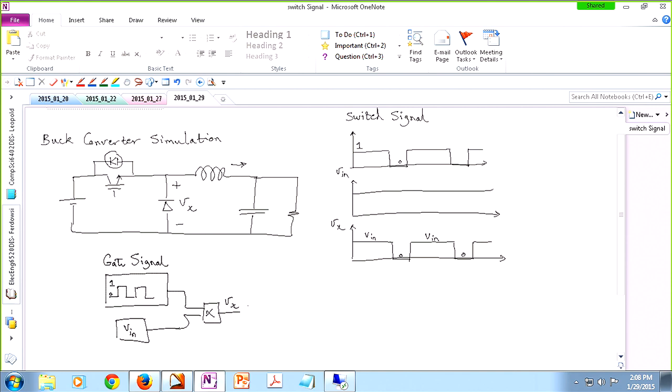Now, if you look at the toolbox, the tools that you have available in Simulink, you have integration and derivation. Try to avoid derivation at all costs, because getting a derivative of a signal is not a very causal way of doing things. You have to have information about the future value of the signal. If you use derivation, you are going to actually end up with some convergence problems.